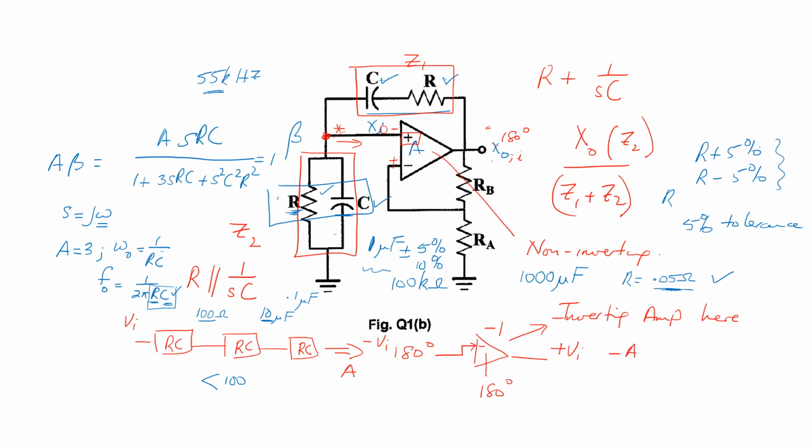In all of these circuits, the frequency selective component, if you like, is the capacitor. So you pick the capacitor first and get the resistors, because it's easy to get an oddball. Say the capacitor is 10 microfarad, and in practice you get R as 540 ohms, just for argument's sake, not that that is the answer for this bit. 540 ohms is not a resistor value you could buy, but it is a value that you can make.